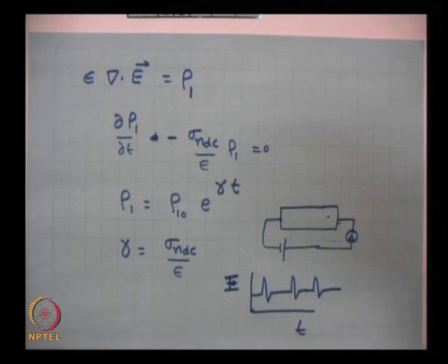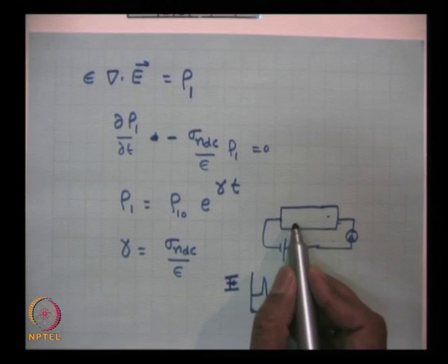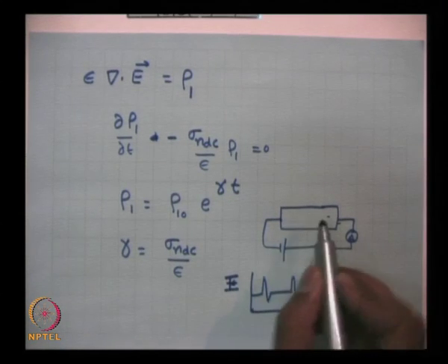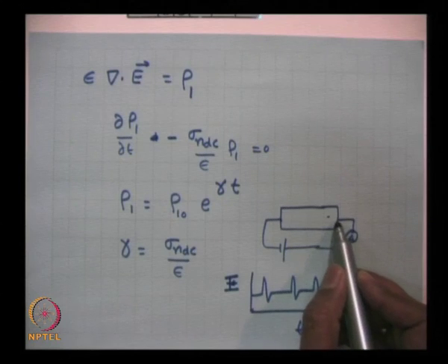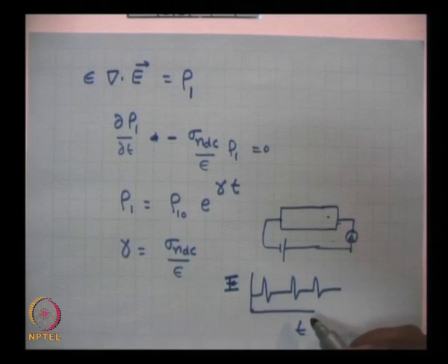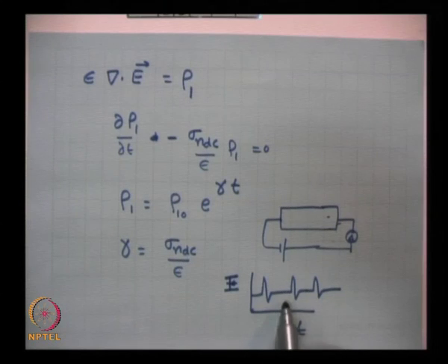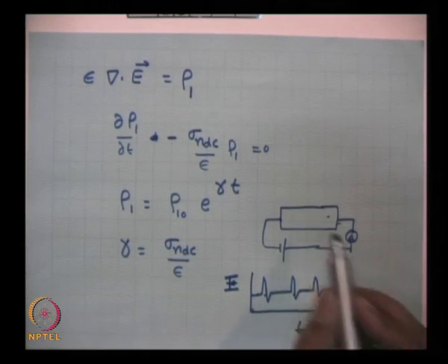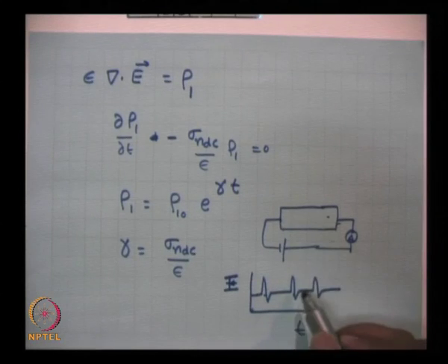So, there is always a high electron density domain and a low density domain created there as a pair, and as it moves out to the wall, you get a sudden enhancement in current. This is a very important behavior, and you can have this frequency of repetition depending on the length of this specimen, and it could be in the microwave range.